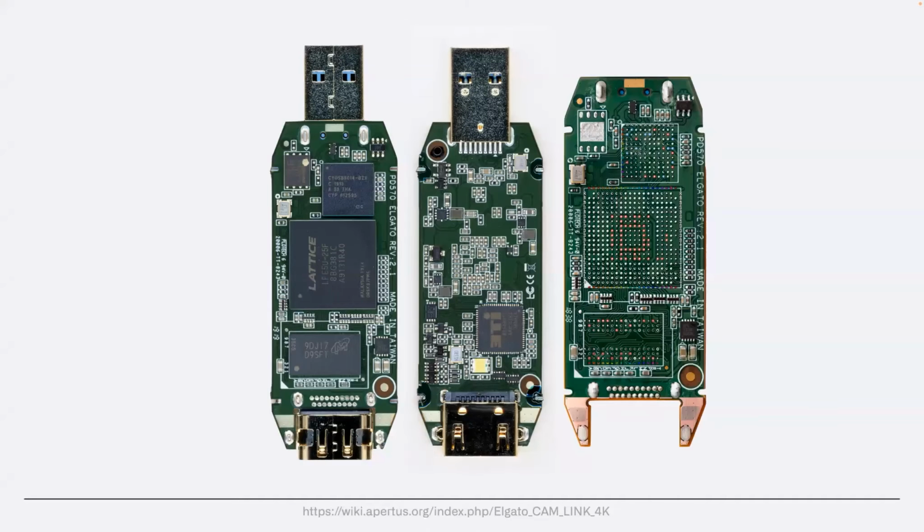And once you open the device, this is what you'll encounter, the bare PCB of the device, which has certain chips, which has tracks going between different components. If you want to go into invasive attacks, or if you want to take apart chips from the PCB, there are also many different ways to do it. But primarily, we are concerned with the non-invasive ways of doing it in this particular session. But in some cases, it might actually need you to take apart that flash chip and then have a custom adapter for it, or have a custom setup where you can interact with that particular chip.